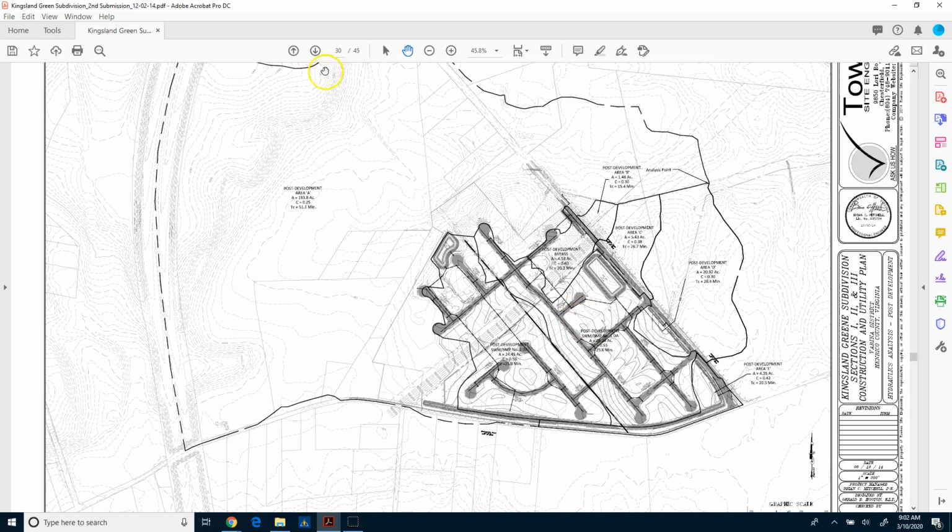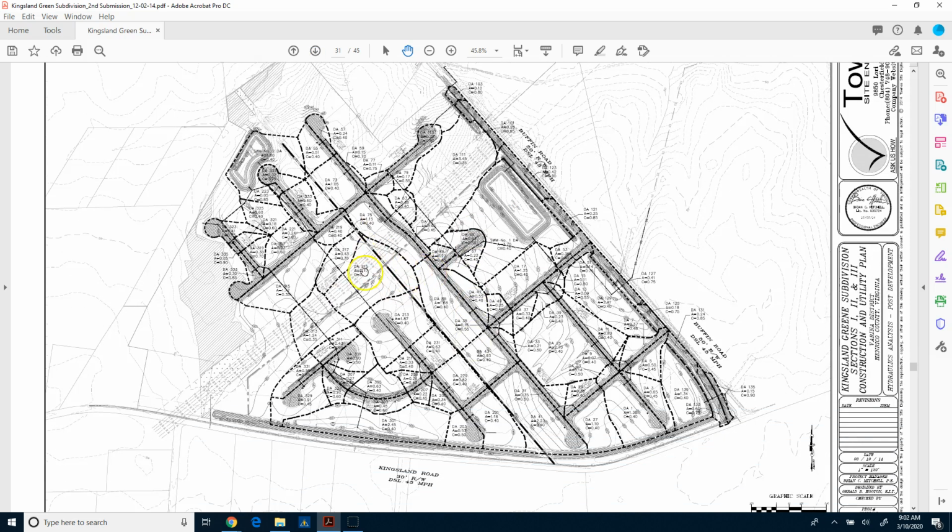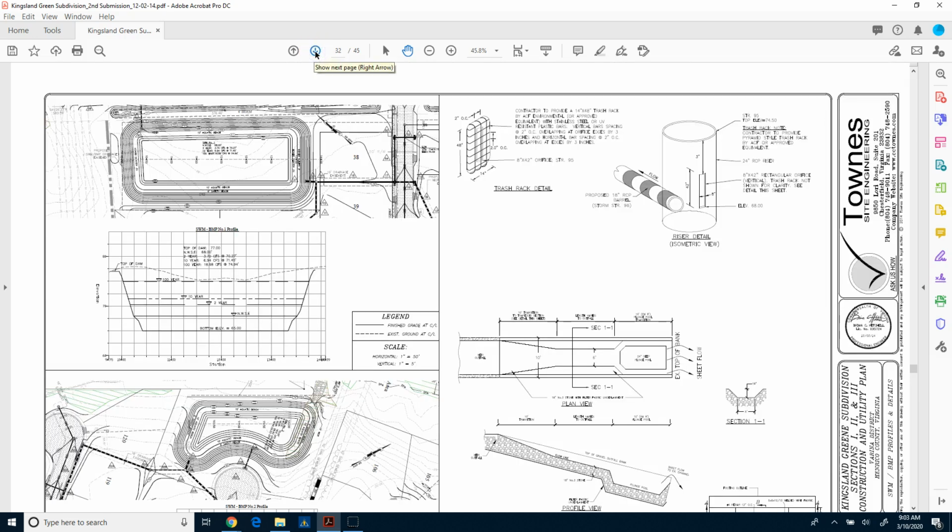And that's why you can see here's a finer detail of all the different drainage areas now that are going to go into these different storm structures. And then it's all going to go into this pond, and basically all the water gets collected into the pond. All the sediment ends up being hopefully filtered out before that water drains off site into the existing or neighboring streams or land. So you want to make sure you're not flooding your neighbor's site when you build these projects, whether it's a subdivision or what have you.